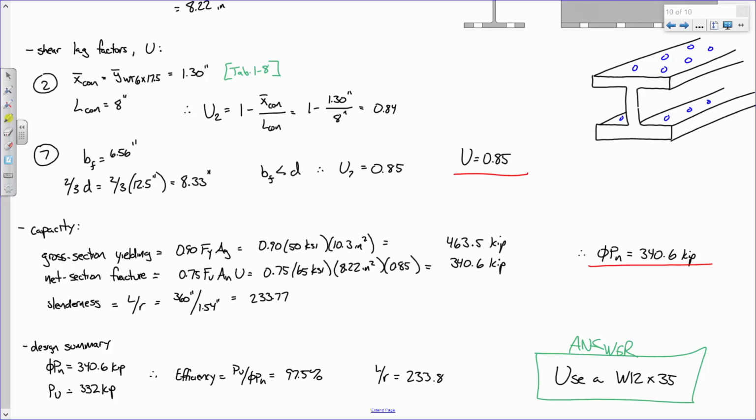Now, you take the Nitro-St. Albans Bridge, it's a truss. Trusses are considered fracture critical because you have a truss here and a truss here. If this truss fails, the whole thing's coming down, or at least it'll result in either total or partial collapse. That is concerning. Because of that, those bridges require hands-on inspection. Their inspection requirements are far more stringent.